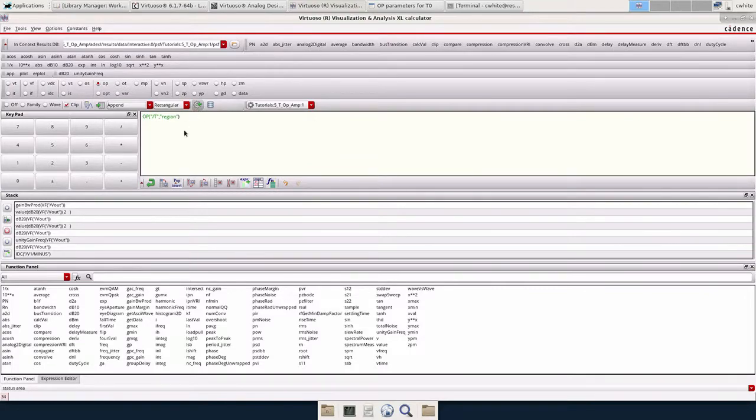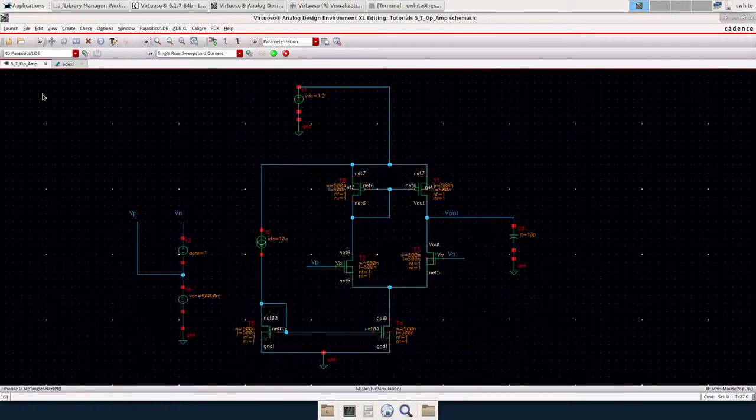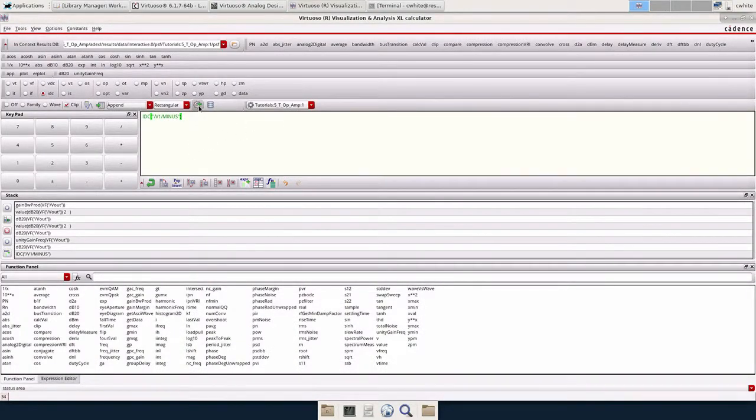Oh, actually, no, there's only 5. So T0 through T5. Also, I don't want the op amp to draw too much current, so I'm going to select the IDC, click the negative terminal of our power supply, and we'll send that too. I'm going to set that to a limit of like 100 microamps, whatever the spec calls for.